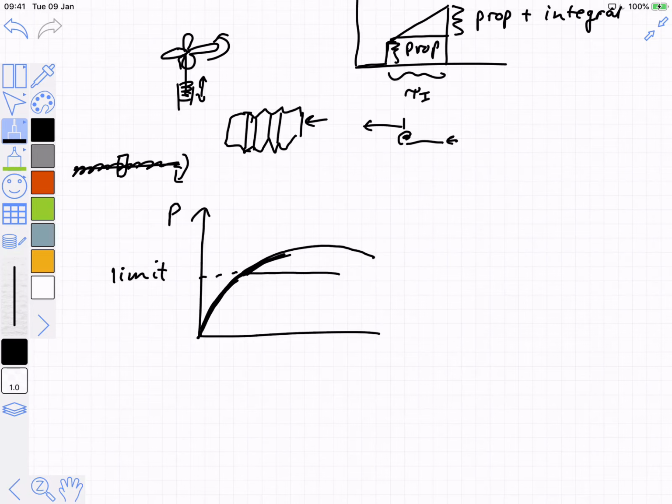At some point, eventually the system comes around, and at this point, here we will say the controller is wound up. So for this entire time, the controller is, well, actually, it's still going up, but it's winding up now because it's increasing the integral without increasing the action.